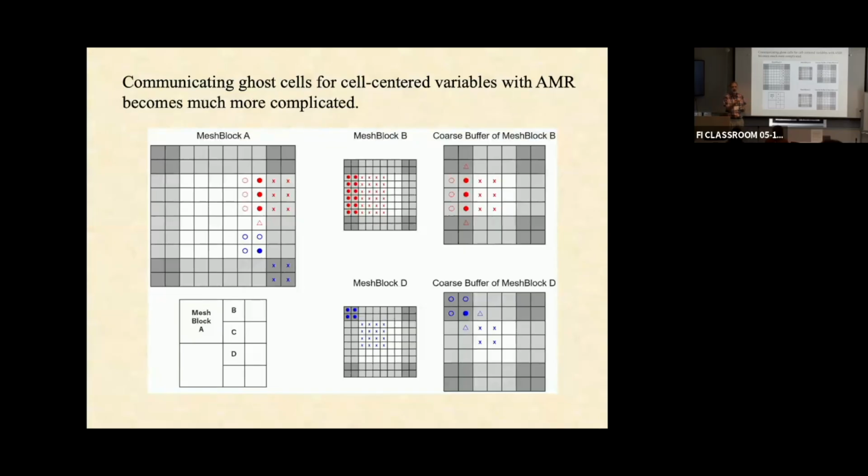If you're right at the boundary of your refinement criterion, with floating point numbers, just the round-off error or truncation error can make you go back and forth on the criterion. So you always want to refine and then leave it alone for 5 time steps or some number of time steps, and then check whether you should de-refine, to make sure the solution settles down to its new resolution and moves forward. You do things like that to make things move along more smoothly.